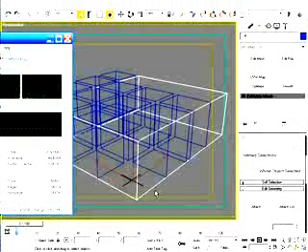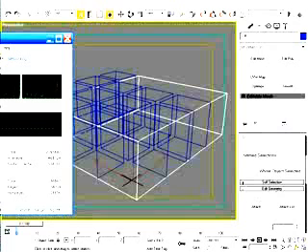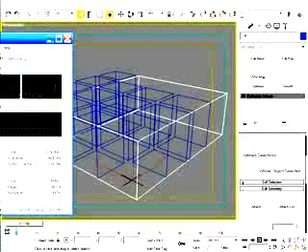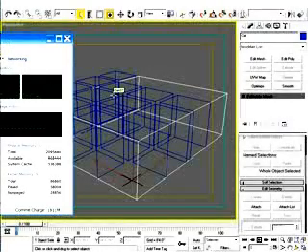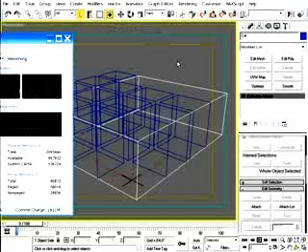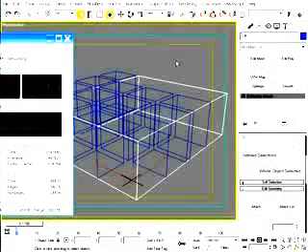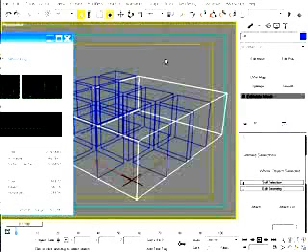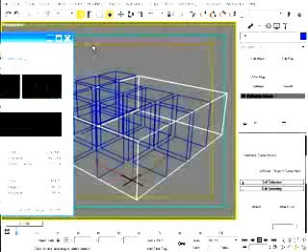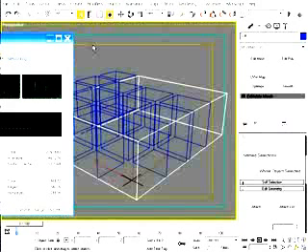Now that attach command that I just executed was extremely memory hungry because essentially Max has to store the original version of the trees as individual objects, and also an additional version with some of the objects attached together. So if I were to repeat this command by adding more trees together, more RAM would be consumed, and before long Max would almost certainly crash. So if I were to start rendering this right now, I would really be doing myself a disservice because I'm giving VRay much less memory to work with. So I should instead free up this memory that was consumed with the attach command and then render the scene.